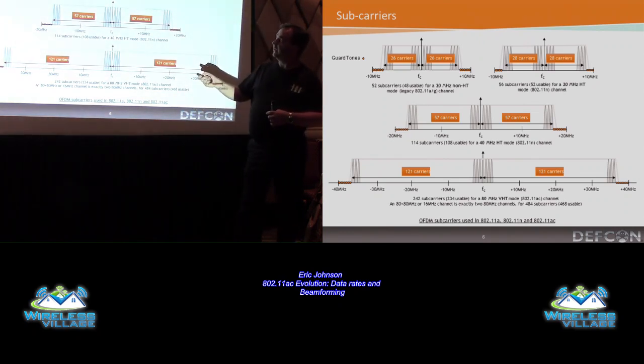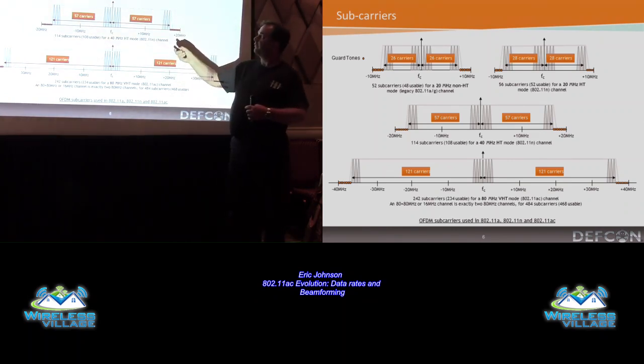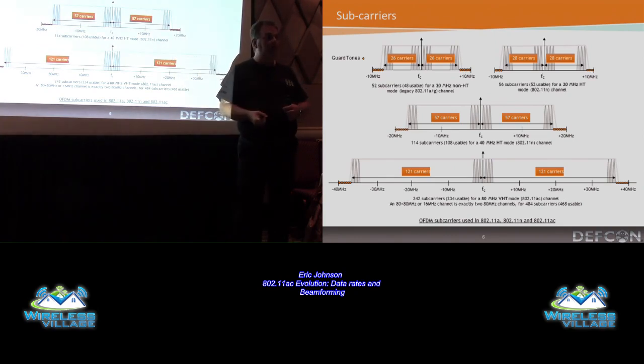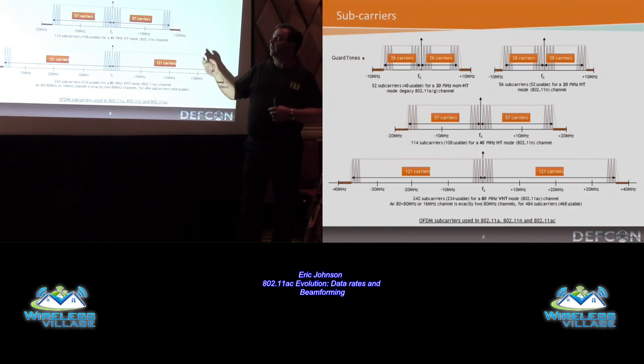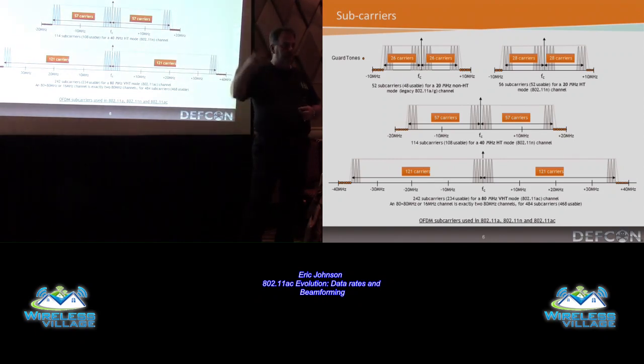So if we go back to 802.11a and G, we had 52. So these things are always based on factors of 2. So the base setup was 64. You have to turn off some tones on each end to create space and frequency. Those are called guard tones, so they have an amplitude of 0. And then there's a couple of other tones in the middle, which are called pilot tones. They contain known information. There's no actual useful transmission of data on that. So those are called pilots. And the pilots are actually used to help the receiver decode the channel and receive the bits.